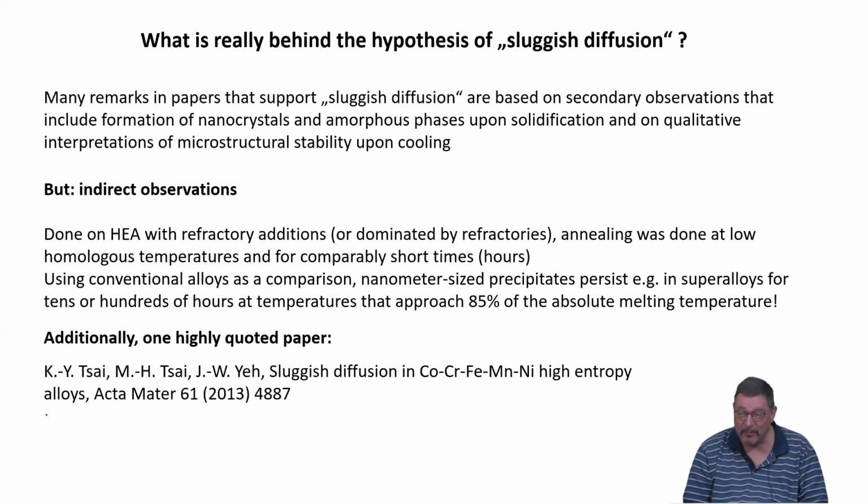It will heat up the material. More importantly, it will cause Frenkel type defects, right? So it will knock atoms out of their position. They go to the interstitial lattice site where they don't like to be, and create also a vacancy. So there's a self-interstitial vacancy pair. And more and more are created, and that causes embrittlement. Also other processes, dislocations are introduced, and so on. And that all leads to a whole range of failure mechanisms.